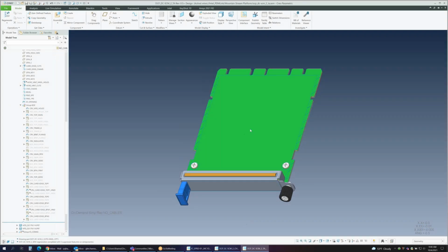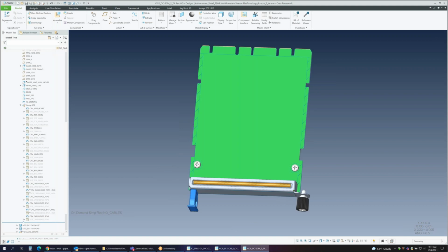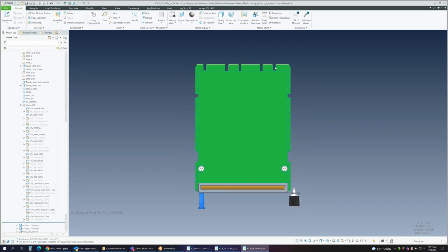Yeah. So maybe I'll share my screen here to just show the changes visually that we're looking at. One of the things we've done is shift the card edge on the mechanical board to the left 3.25 millimeters. Based on the tolerance analysis, that is enough to make sure that a DCM 2.0 card would never insert into a 1.0 slot, and vice versa. That's ratified and implemented here.